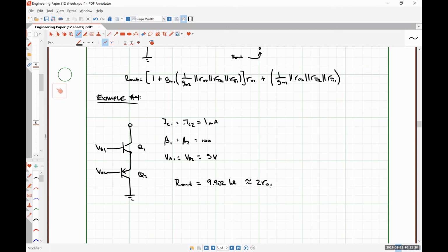There is a technique called folded cascode, which is beyond the scope of this course. We go over it in 438 for those of you who haven't had enough of this by the end of this quarter and want to do more of it in the spring, where you effectively fold at the cascode node with an opposite technology transistor, but it's configured in such a way that it doesn't jack things up like this. It's hard to describe without getting into great detail about it. So there is a use for connecting an NPN to a PNP, etc. But this configuration isn't how to do it correctly.